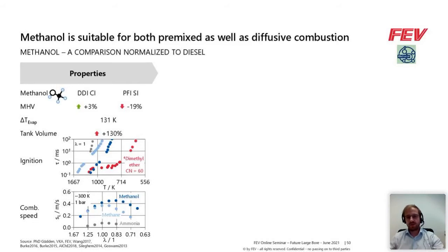However, the value on the engine isn't as severe, as we also have quite severe evaporative cooling with methanol. In both cases, considering the energy density, we would need to increase the tank volume for methanol by about 130%. And finally, regarding the fuel properties, moving on to the more combustion-related properties.